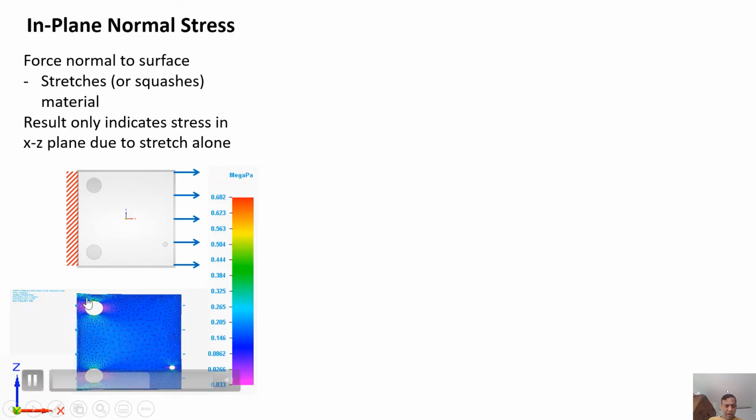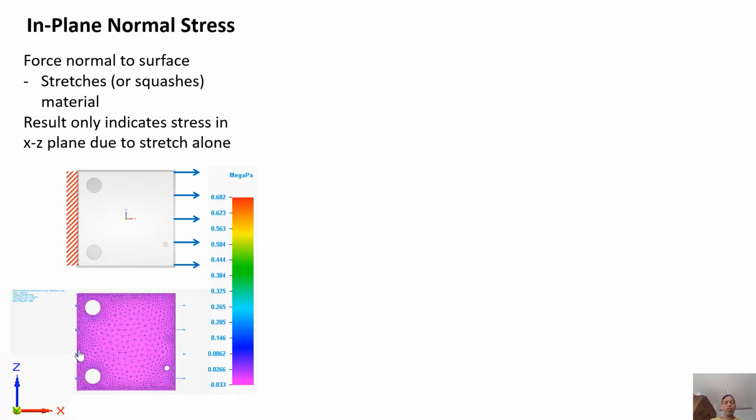And you can see that there are some purple color stretches, and even the blue color stretches which are coming in this range. It's difficult to see the red patches here. So this is high stress and these are low stress, but we can see some stresses here, and this is the fixed constraint. That means we are fixing the plate on that side. So these are normal stresses.